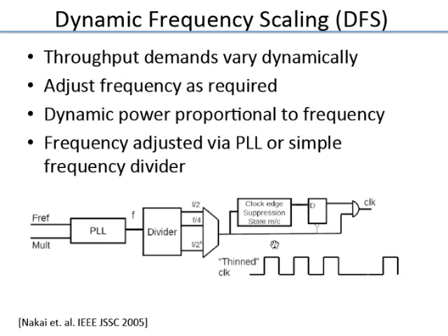What these guys propose is what is called clock thinning. They have a little state machine, and what is frequency at the end of the day? It is some number of edges per second. So if instead of 32 megahertz I want 31 megahertz, it is 31 million edges per second, or per microsecond, it is 31 edges. So you just count and you suppress. That's what they do. That way they can adjust the clock frequency.